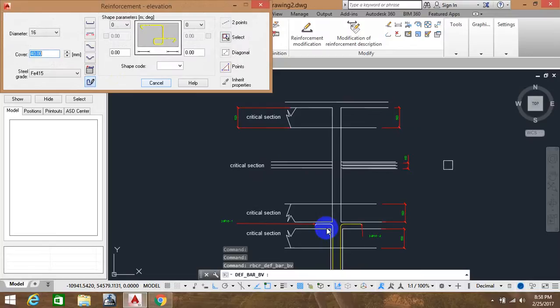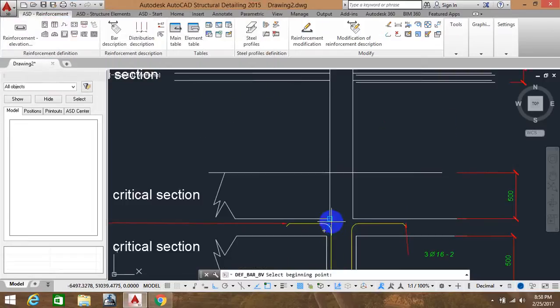Sometimes a student asks me about this length, how much is this length after a bend. It's LD, the development length after a bend when it takes place from this point. It's 16, so 16 into 50, and you get the development length. It's 16 into 50, I just got 800 mm. So it's 800 mm after this point. Just don't get confused by this also. These are the basic points, so I'll tell you in these classes.